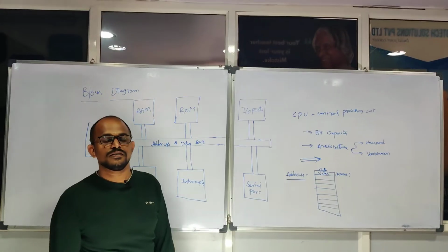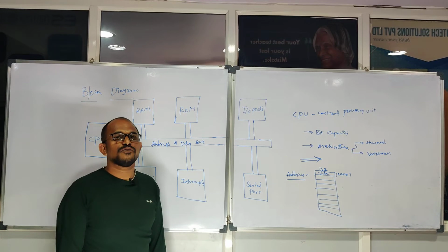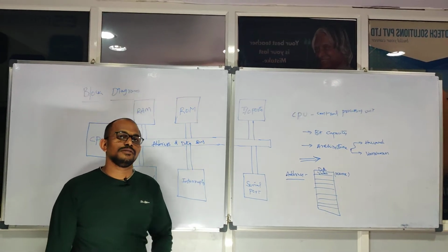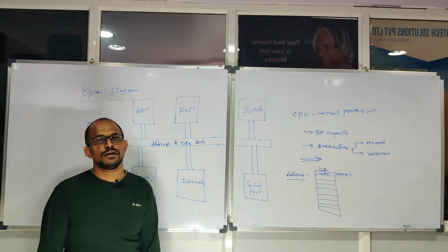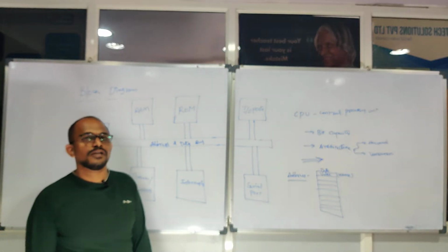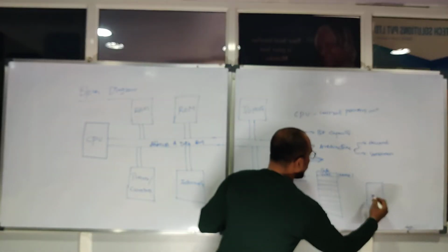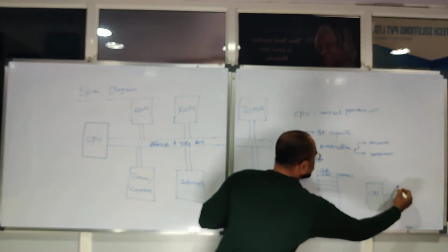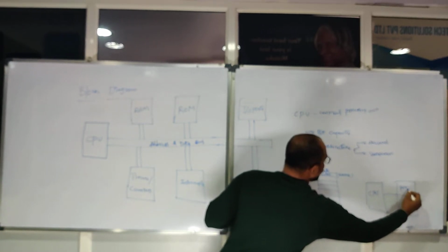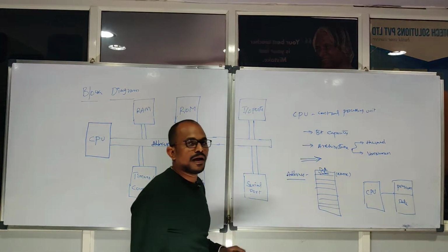Another difference in architecture is that if the processor follows Harvard architecture, you will have separate data memory and separate program memory for controllers. And if you have Von Neumann architecture, you may find the same memory for program and for data. The same block of memory is divided into two parts, program memory and data memory.